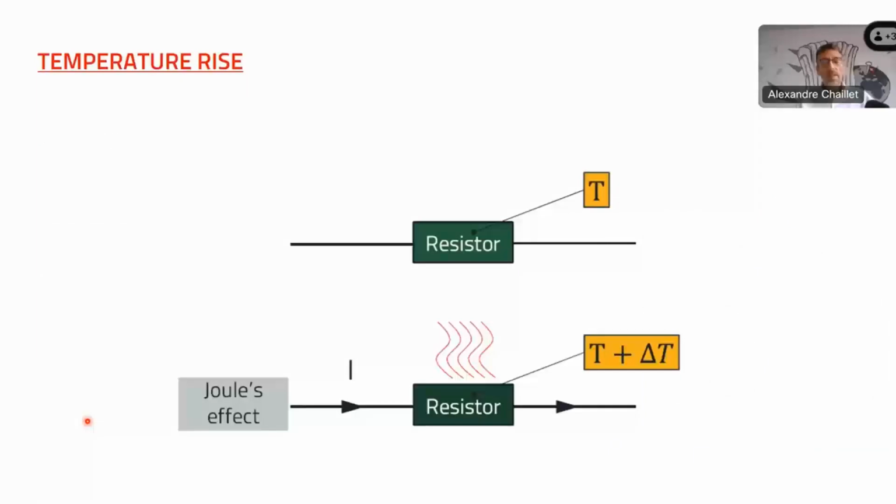So now, consequences of high temperature. First, a little bit of vocabulary. A connector for power could be considered just as a resistor, such as a trace. That's, of course, different for data traces, but we are talking about power. So this is a resistor with an ambient temperature T, usually given in degrees Celsius.